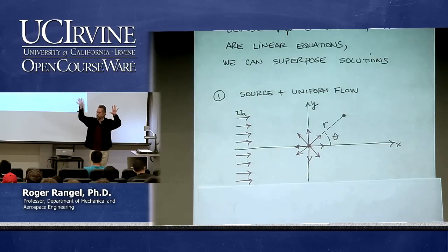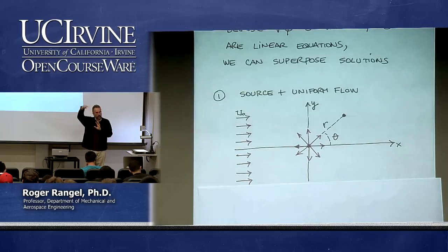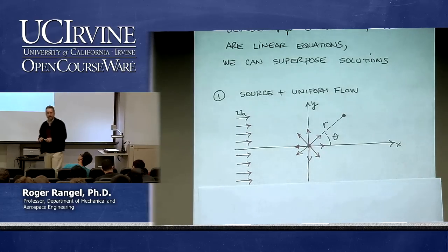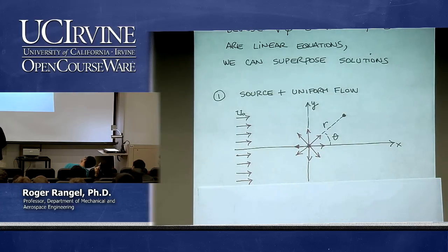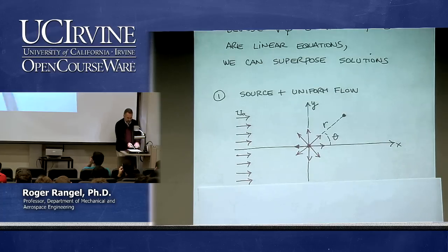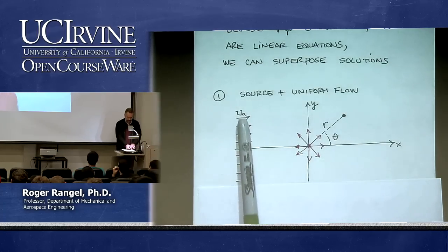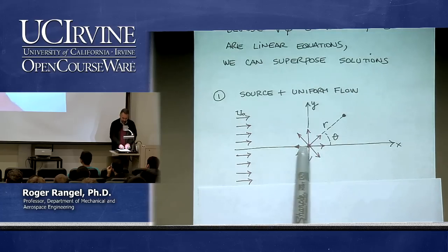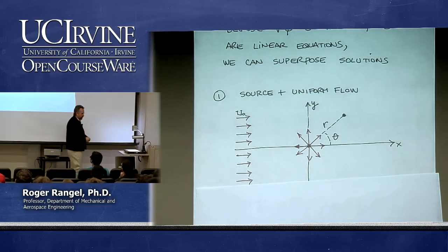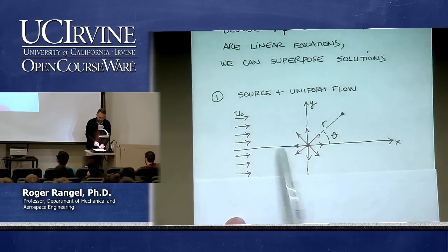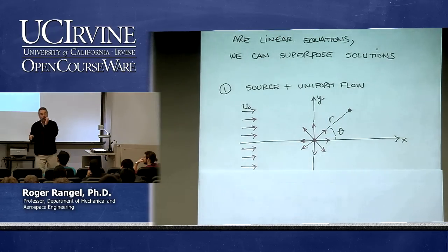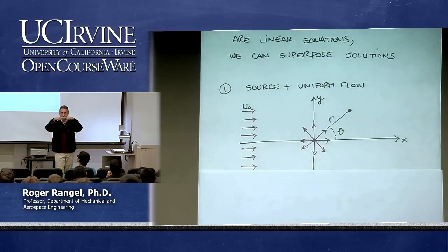And then it decreases as the flow goes out. Right? Because it's proportional to the inverse of r as it goes out. So it doesn't cancel here at the center, but can it cancel somewhere else? On the x-axis, which side of it? The negative side of the x-axis, because this velocity is always u naught to the right. This velocity, as I move from the origin out, decreases from infinity to essentially zero if you go far away. So obviously at some point this velocity will have the value of u naught on the negative x-axis. Everybody see that?